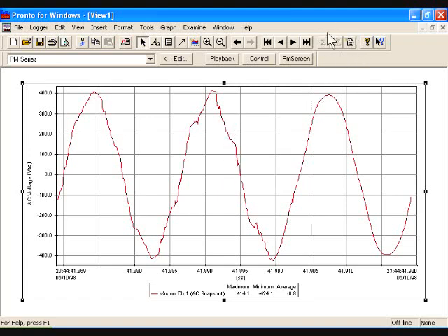But first, I want to take you up to the top of the screen here, and I want to show you that the Greek letter sigma and another thing here that looks like harmonic bars are in shadow, and you can't click on them now. That's harmonic analysis. But once you select the waveform capture by clicking with the left mouse button once, and you put these little boxes on there, now if you go up here, you'll notice the Greek letter sigma is out of shadow, as well as the harmonic analysis. We're going to click on harmonic analysis because that's what we'd like to do now.